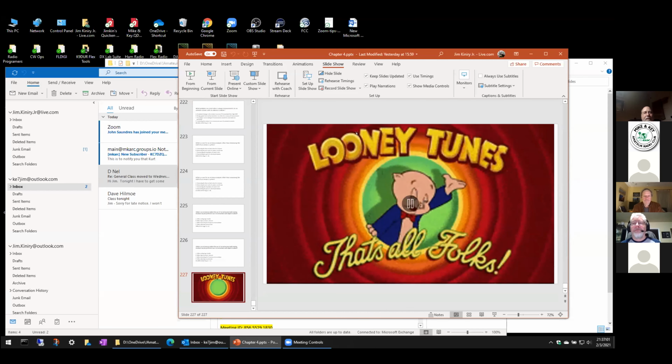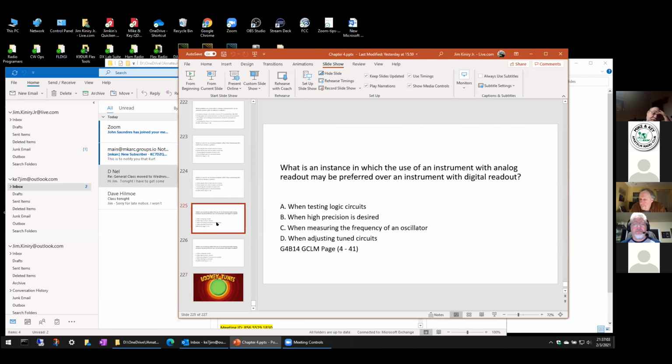On that last question, when you're doing a tuned circuit, you'll see a dip in the current, the plate current, and that is not picked up with the digital meters. But you'll see the needle make a dynamic dip down when it hits maximum power transfer at the tuned point. You'll see it on the needle, but the digital meter will not recognize it. I still have an old dip meter with the different attachments that you can plug into it.